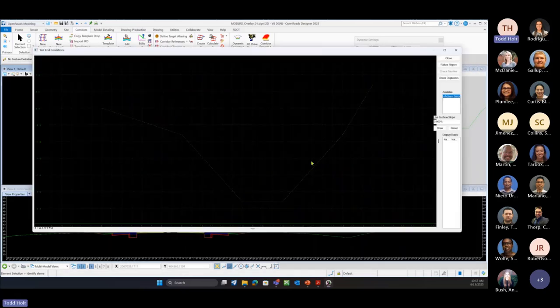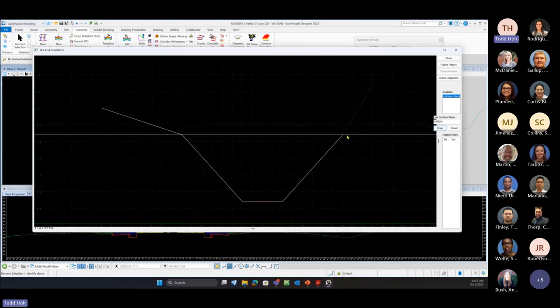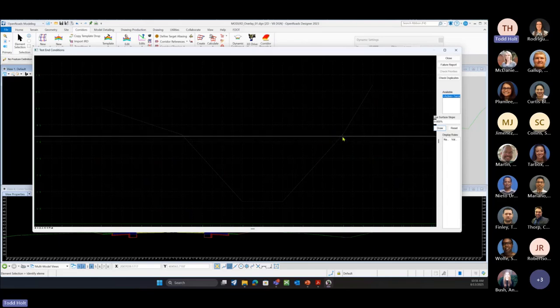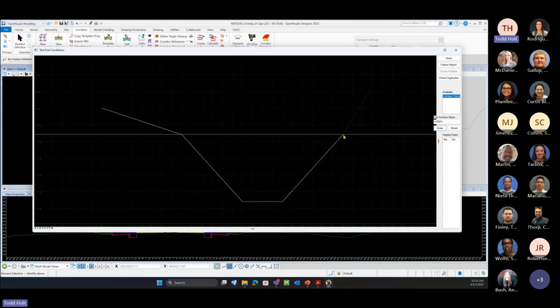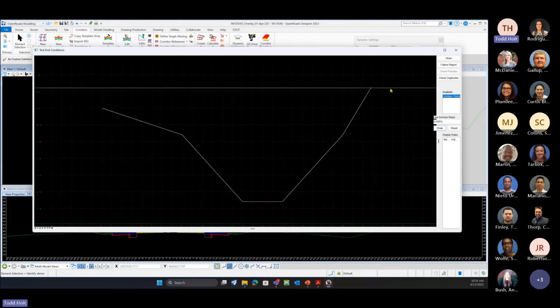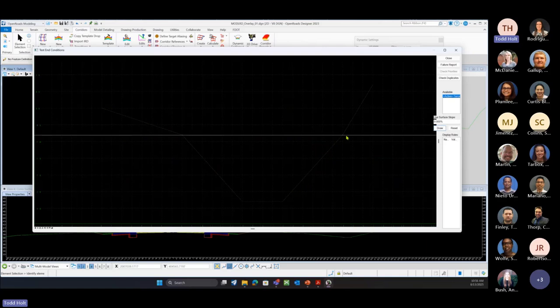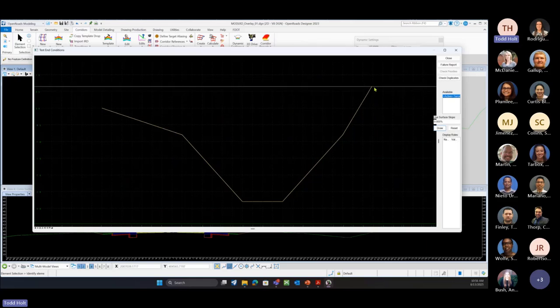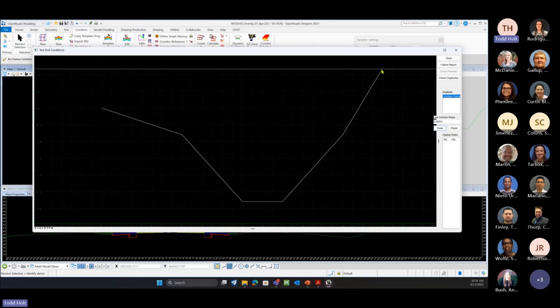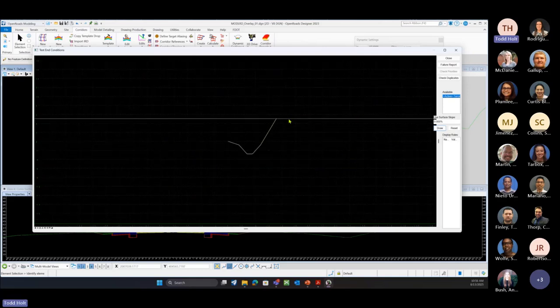So let's test that out to see what it's doing. If we test this, we can draw this out. Right. So here's our point. If we don't cross that point, we can go up to that point. It's not going to draw. It's only going to start drawing once we place the point intercept after that point and out to that end condition. So it's going to solve for that and draw. So this point is really controlling how we want that ditch to draw. So it's going to come back and find that existing point, and then it'll go up and solve for that. So from that point out, it's going to go and solve infinitely away from that.